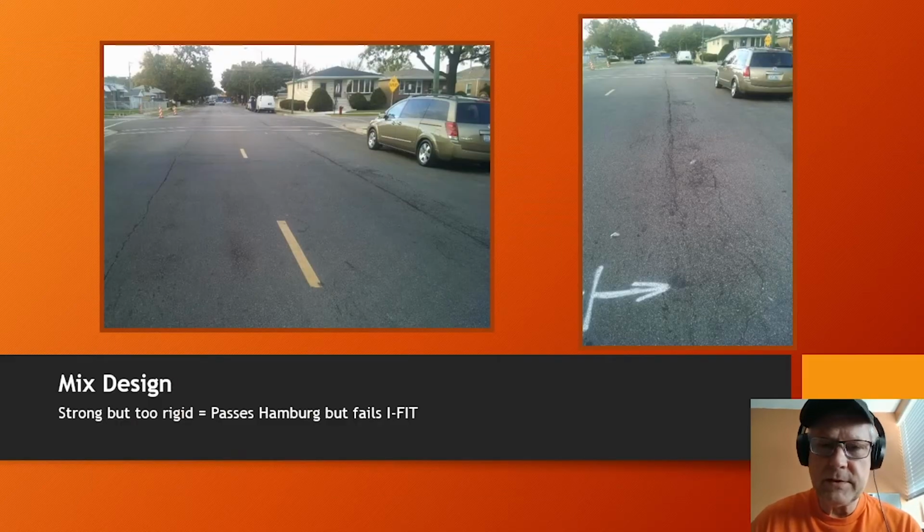This is a mix that's not even 6 months old. It's a local agency asphalt, very, very high recycle. Paving seams are pulling apart already, probably some thin asphalt installation. And on the right side, you can see that the joint's already failing on both sides. It's very strong, rigid pavement. We want flexible asphalt. We want asphalt that stays together. This was really a very tragic application of very, very high recycled asphalt in a local agency specification.